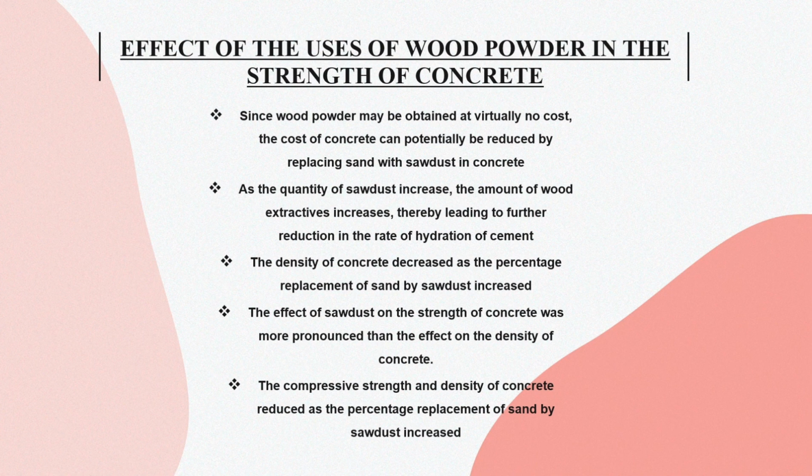The effect of sawdust on the strength of concrete was more pronounced than the effect on the density of concrete. Finally, the compressive strength and the density of concrete reduced as the percentage replacement of sand by sawdust increased.